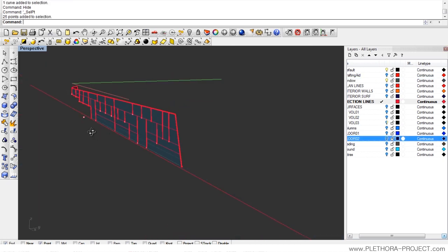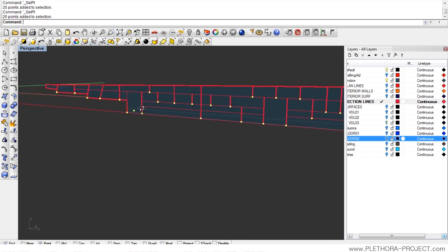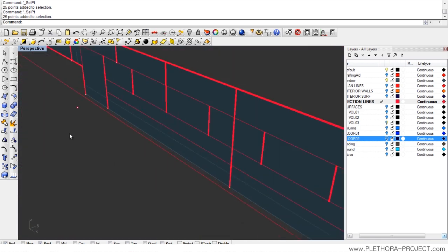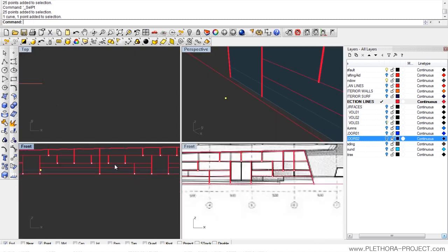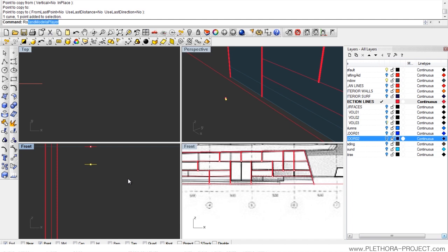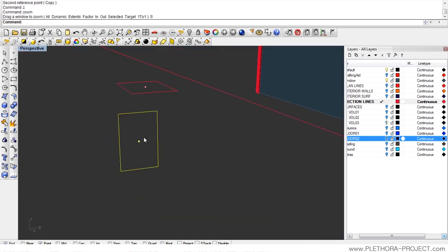Right, so you can see now that I have positioned basically where the points are different profiles, and I basically kind of sweep them up, right? The only thing that we're missing is the ones that go horizontal. So for that, I'm just going to pick our little profile here. That is somewhere here. We can make a copy of it so we can stick with the other one as well. And I'm going to rotate this one. So rotate 90 degrees, so we can see that we have it in this direction now, right?